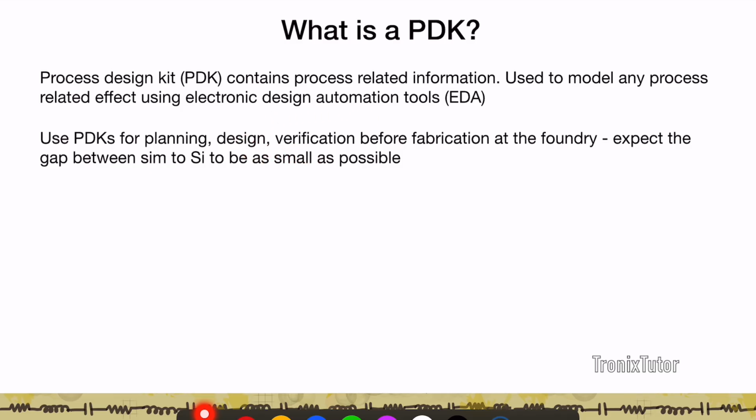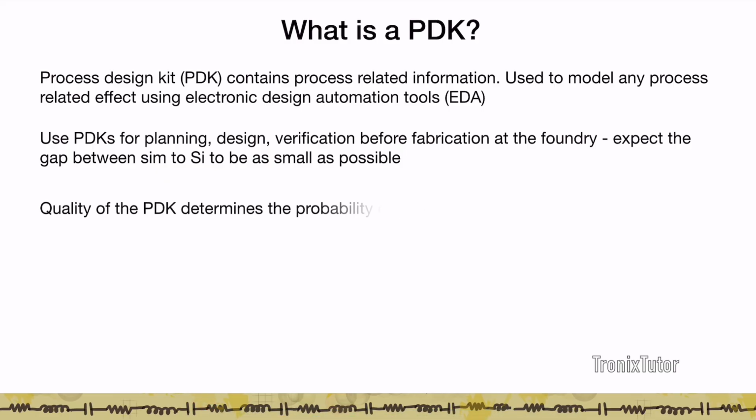And remember, design tape out is a very expensive process, right? Depending on the node you're working in, this can be a multi-million-dollar project. And so to ensure that you have good success in your first attempt, it's important that this PDK captures all the information of the process and reliability in a conservative fashion, so that your simulation to silicon gap, when your first silicon comes out, is small, so it's predictable, right?